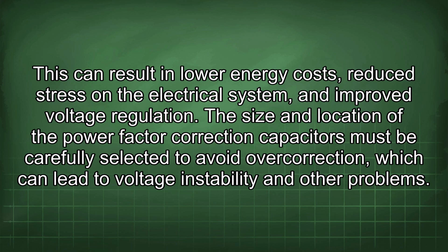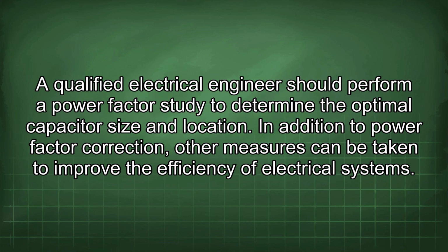The size and location of the power factor correction capacitors must be carefully selected to avoid overcorrection, which can lead to voltage instability and other problems. A qualified electrical engineer should perform a power factor study to determine the optimal capacitor size and location.